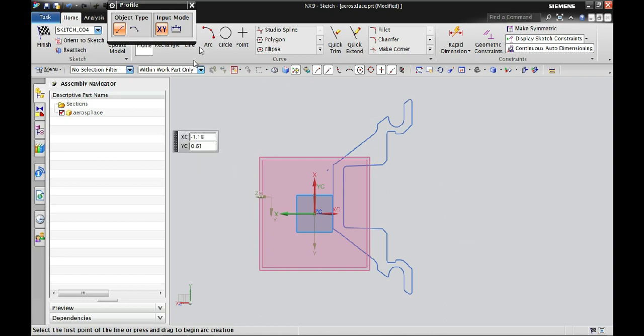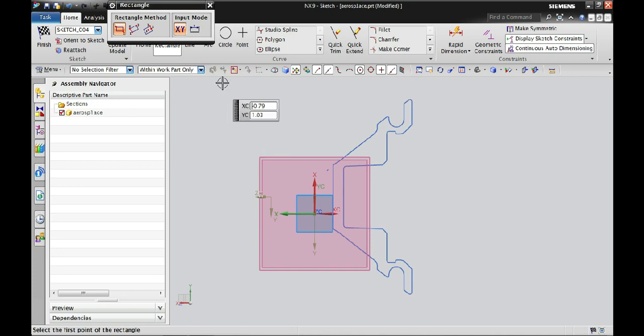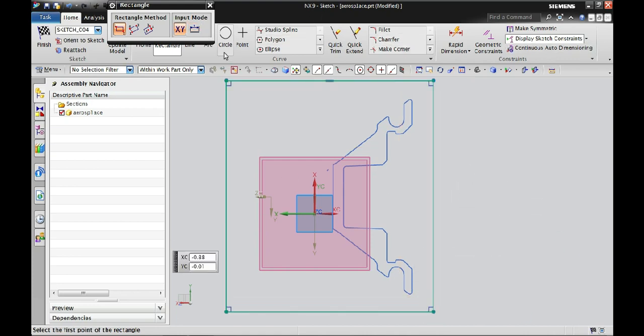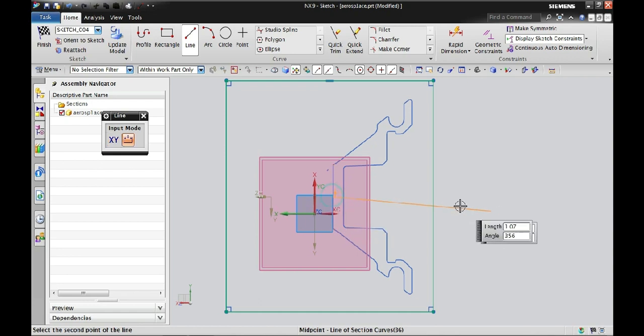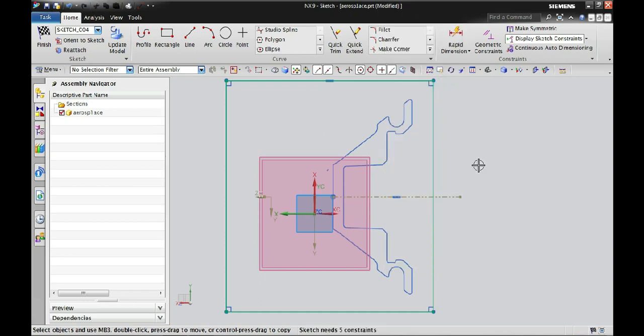Now let's create the stock around it. Turn on the continuous stuff here. Okay, so now, depending on how you do it, if you're metric, all you need is only 0.1 millimeter of stock on the top to clean up, and on the face the same thing.